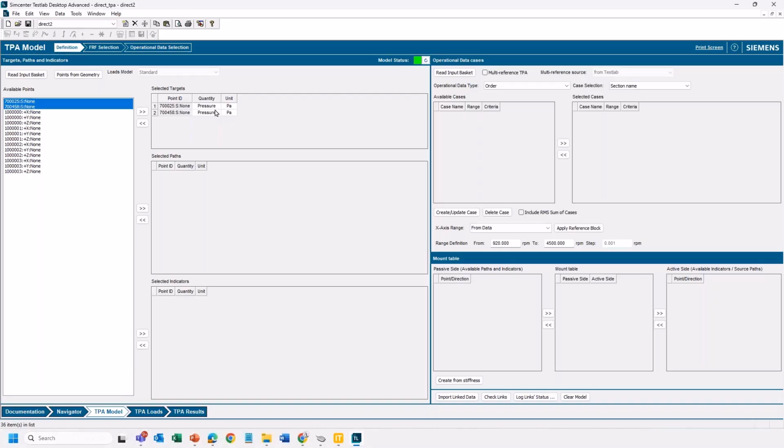And you can have more than one target. We showed an operator ear before, but you could have the operator ear. Maybe that's what this one is. And then you could have the passenger ear, because maybe a car company cares about the passengers, or even the rear seat passengers. There's no limit on the number of targets. You just have to measure the FRFs from the force inputs to those target locations.